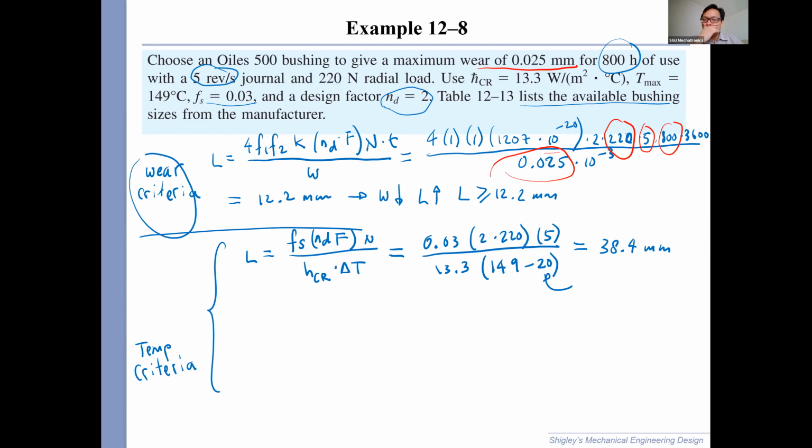And explain. Because in the equation, the delta T is in the lower part. So if the temperature is not 149, of course the L will be increased. Right. So if you want to operate colder, yes, you should increase the L. If the denominator goes down, L will rise. So the relationship is an inverse relationship. If you want it colder, then you have a longer bushing. Shorter bushing, you will develop heat more, which makes sense if you think about it, right?